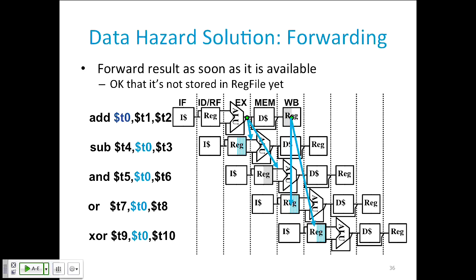Well, the general case is actually pretty straightforward. For any instruction, you decode it and find out, does this instruction write a register, right? If it writes a register, where does it generate the value that it's going to write to the register, right? So all the ALU instructions all produce the value here. They do write a register and it's ready here.